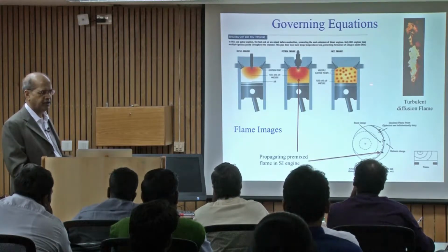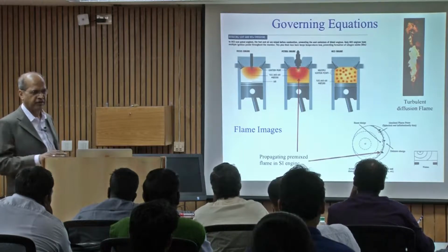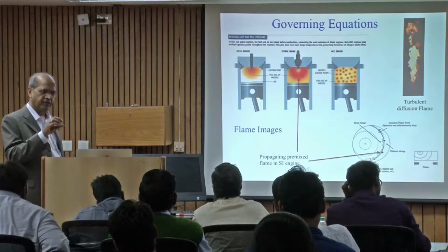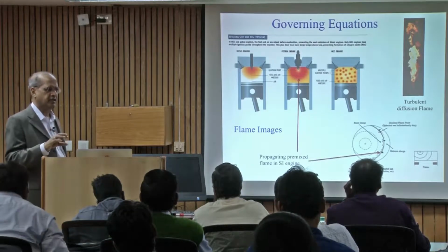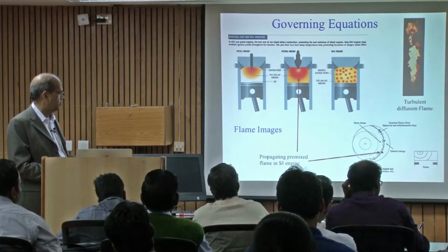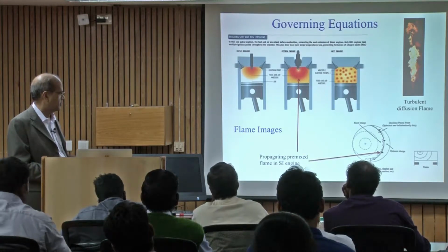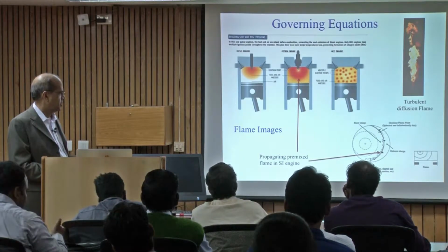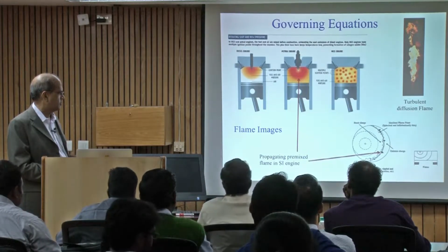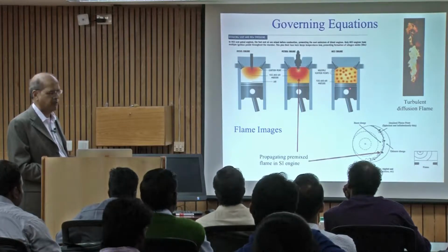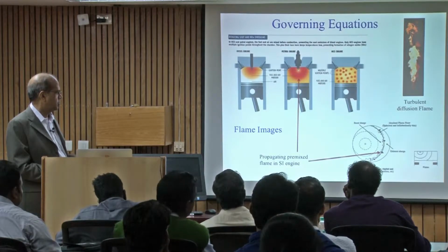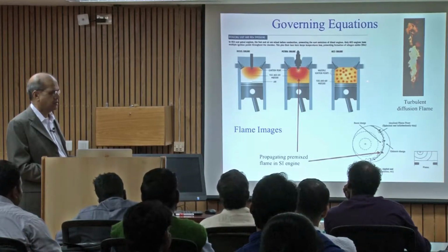Of course, you cannot make it exactly uniform ignition everywhere. Okay, that's the ideal condition. So instead, what you have is a lot of spots where ignition can occur. Okay, so all these reds are where you have the ignition, called multiple ignition points. So again, in this kind of combustion mode, the flame structure, I should say, is very complicated. A lot of work is going on on how to control the ignition process in this combustion mode.